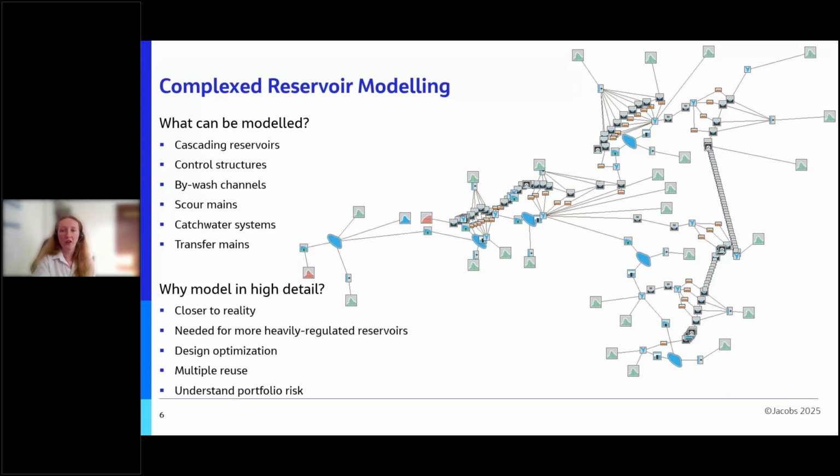We then use the final annotated stage and outflow results as inputs into a reservoir risk toolbox, and the stage in relation to the clay core and the time and depth of head above the core feeds into the geotechnical assessment of dam failure due to seepage. We also need accurate still water levels to feed into wave overtopping calculations, and more realistic assumptions are also needed for design optimization, for example, or even just to determine the level of draw down a reservoir by for safety reasons during construction on the site.